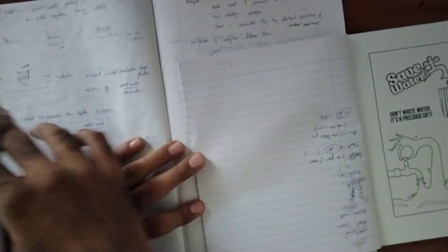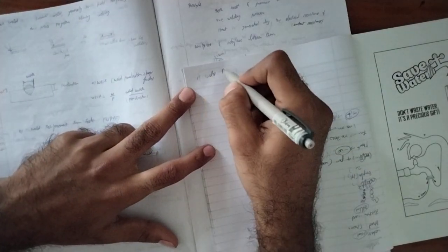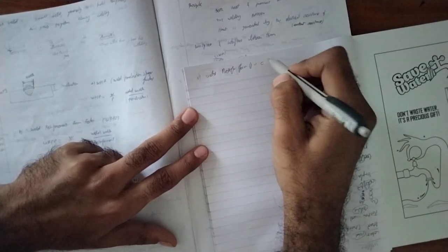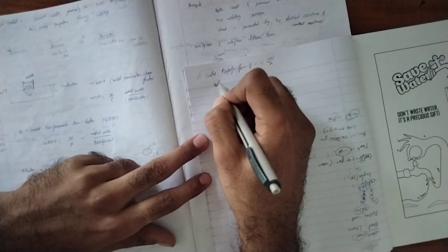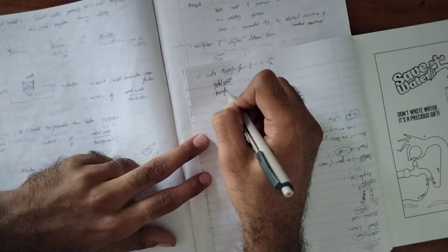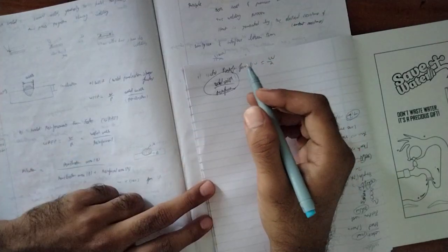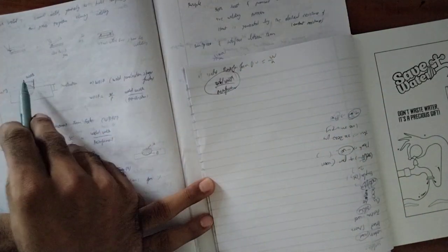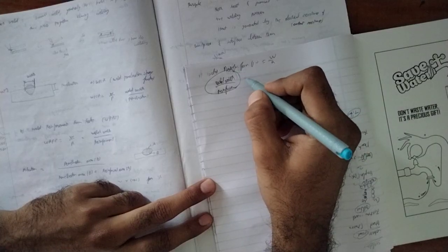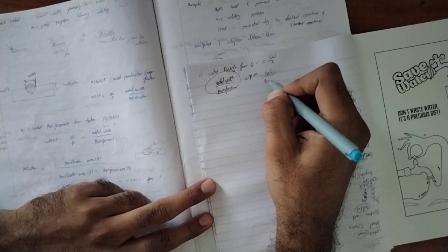So next one is weld reinforcement form factor, equal to W divided by R. It means weld width divided by reinforcement. You can see this one is the weld width, and this one is the penetration. So the weld reinforcement form factor, WRFF, is weld width divided by reinforcement.